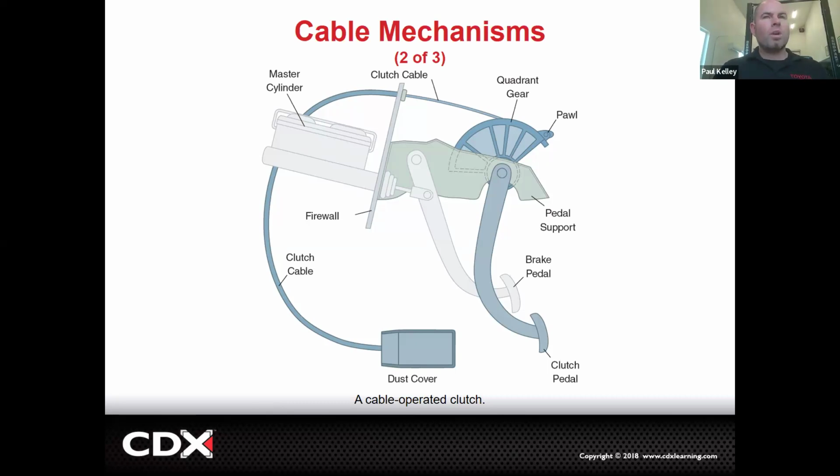Makes sense? When you release the clutch pedal, you should have a little bit of wiggle on that cable, on that pedal. You should be able to feel just a little wiggle. If there's no wiggle, that means it's actually pulling on the clutch fork and it's partially disengaging the clutch at all times. You understand? So how much wiggle room?